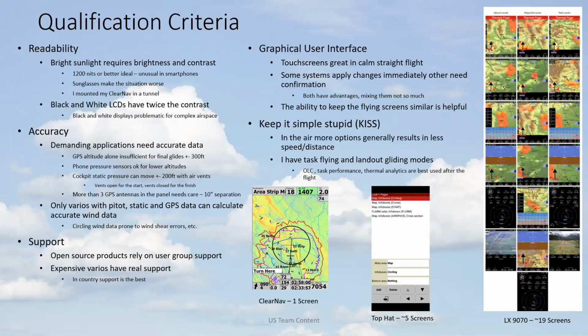When you're doing cross-country flying, you could be in waypoint mode, where you're going to a waypoint, but you haven't got a task programmed. And in airport mode, you're generally going somewhere where you're going to land pretty soon. So that's all focused on gliding to a particular landing point. And you'll see each of these modes has different screens associated with it.